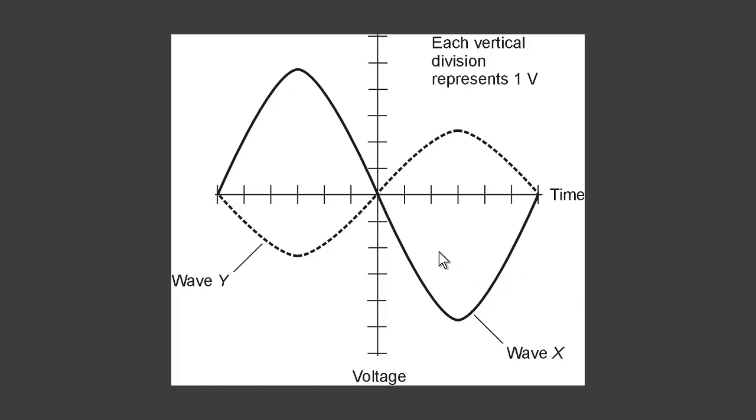The question asks us about two sine waves, the same frequency, but 180 degrees out of phase. Neither one of them has a DC component. So both of these are pure sine waves, exactly opposite in phase, and therefore the voltages at any instant in time will add together point by point. For example, here the composite wave will have a 0 voltage. Same thing here, same thing here.